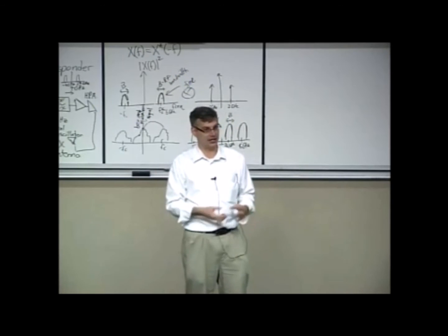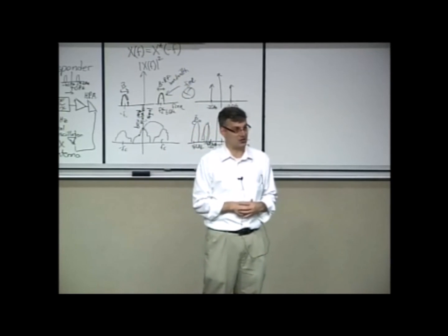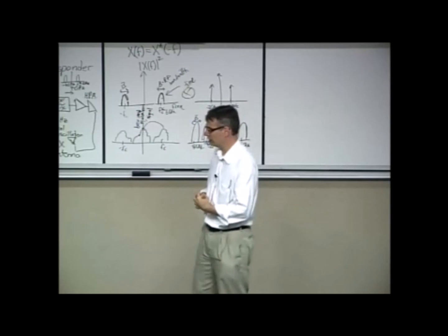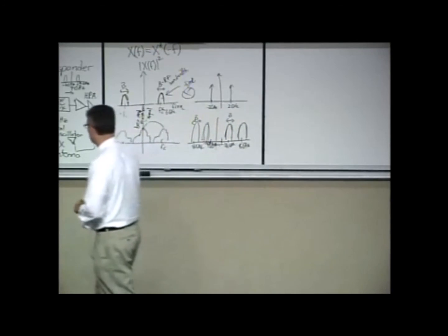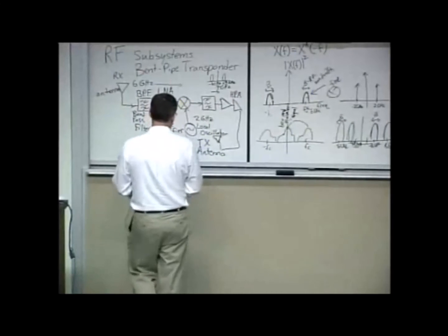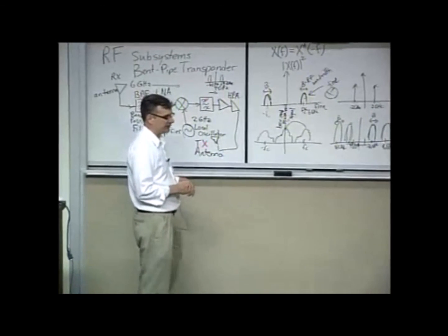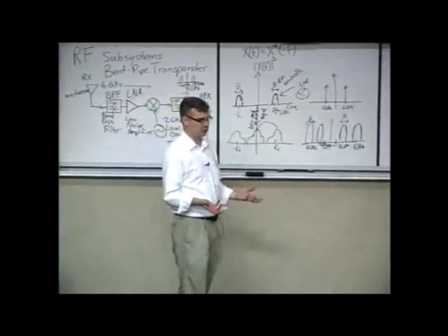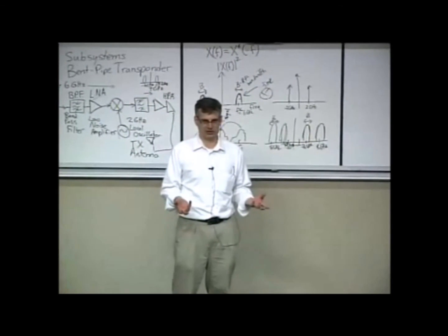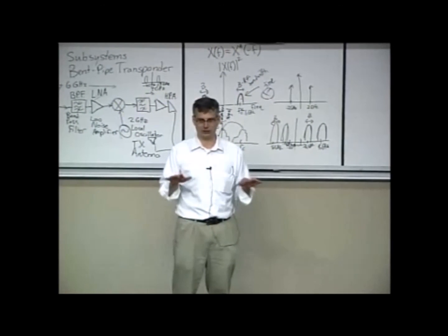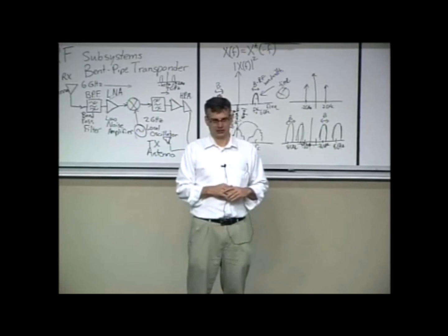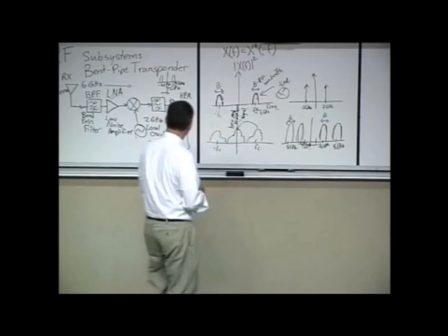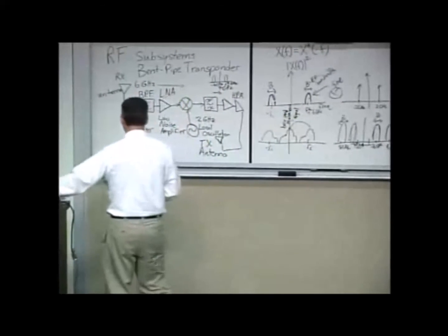You can engineer it to almost an arbitrary level of accuracy and precision. You just need to have the right ingredients: bandwidth, signal strength, etc. And so if you can regeneratively repeat the signal, you tend to get a much cleaner, low bit error rate transmission of data, particularly digital data. And so this is what a more modern